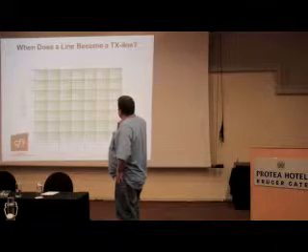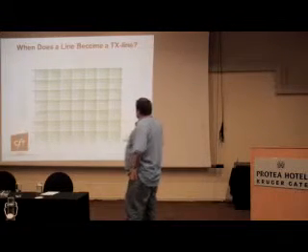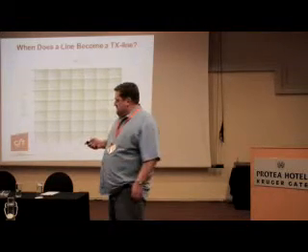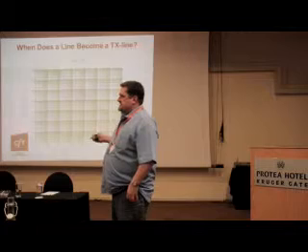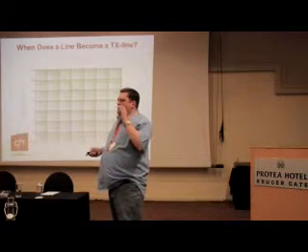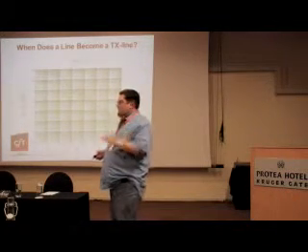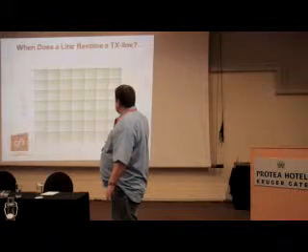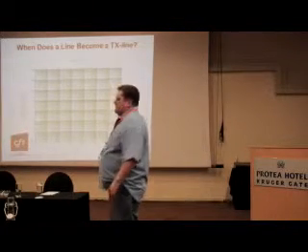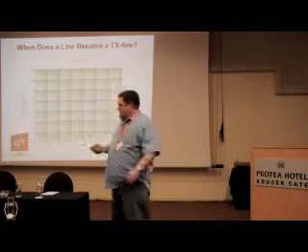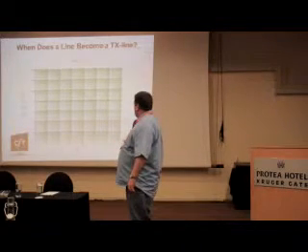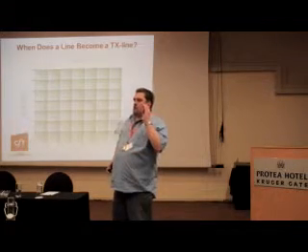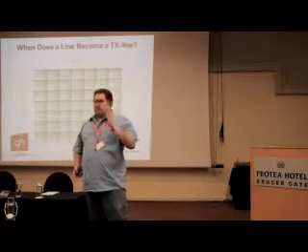So, suffice to say that at some stage the line becomes a transmission line, but for the Cenelec bands, you can almost always use lumped circuit analysis, because you're talking about typically 100 meters before the line becomes a transmission line. But if you're talking about broadband in the megahertz, 30 megahertz range, then it's almost always a transmission line.